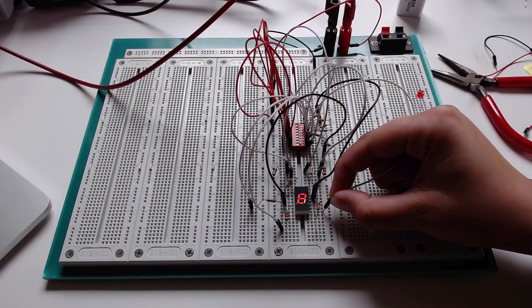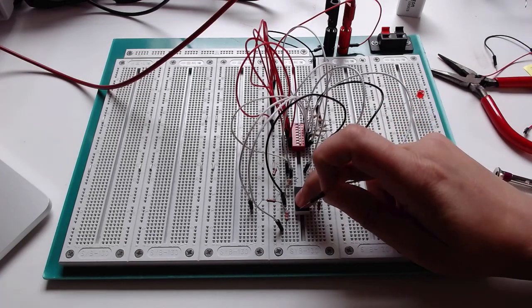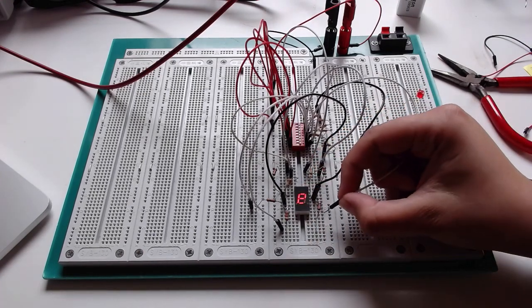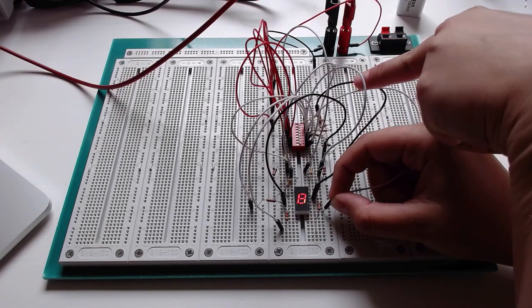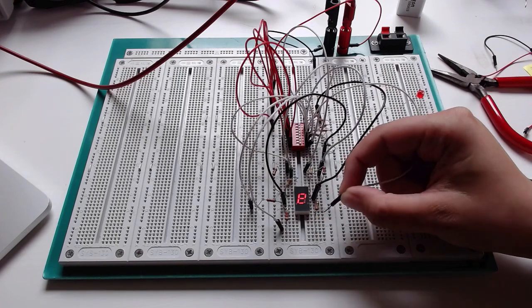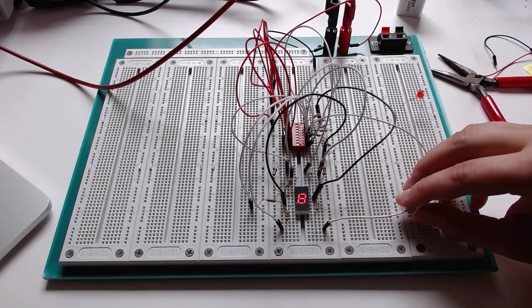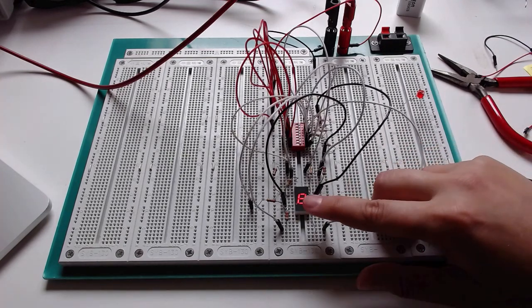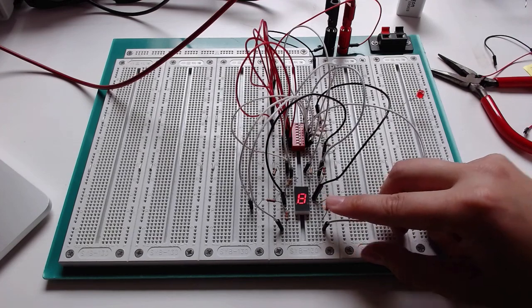Now look at what's happening to that LED. It is turning orange, and if I touch it, it's actually really warming up. What happens when I do this is that the 5 volts is coming directly from the signal wire to the LED without going through a resistor. It needs to go through the resistor. It has to. So we can't just bypass this resistor. It has to go through the resistor.